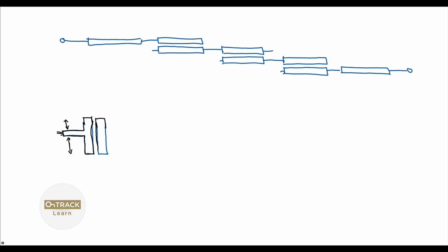We can do it this way, and then this would fold over. That's a quarter wave. We carry it on. So we've got a little bit more transmission line, enough to separate it so it doesn't couple on itself. And that may come to another segment that's coupled. And then that may go around to further segments.